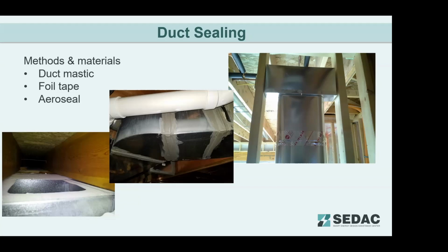In the center picture there, you're seeing a picture of duct mastic. This is a paste that comes in a pail and it's applied, hopefully thick, in a very thick coat. Some people call it painting ducts. I wouldn't use that term because paint is a very thin material. You basically want to apply it as thick as a nickel when you're using mastic. So you shouldn't be able to see any gaps or seams in the ductwork when you see the mastic, and I often do. And if we put a smoke machine on it, you'll see smoke coming right out of it.